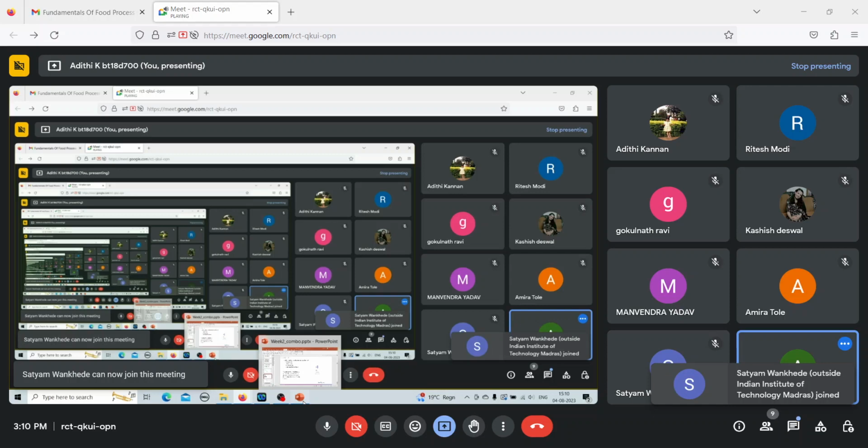And again, for a viscous fluid, the relaxation time is very, very small because the stress will immediately drop. For an elastic solid, it will have the same graph as this, which means it will never drop, so your relaxation time will be infinite. I hope this is clear. Based on this, your Deborah number will also change.